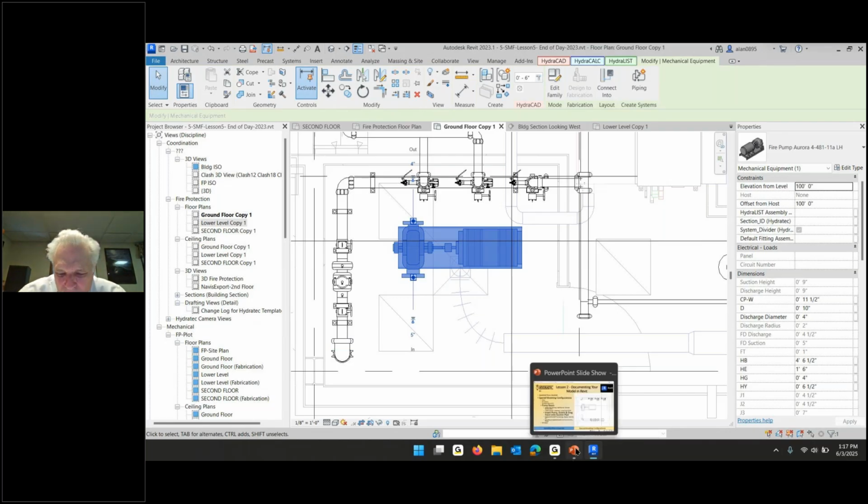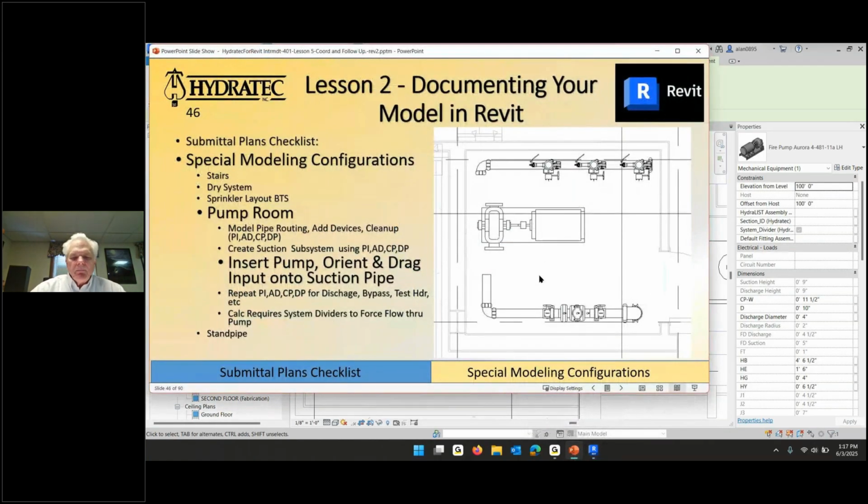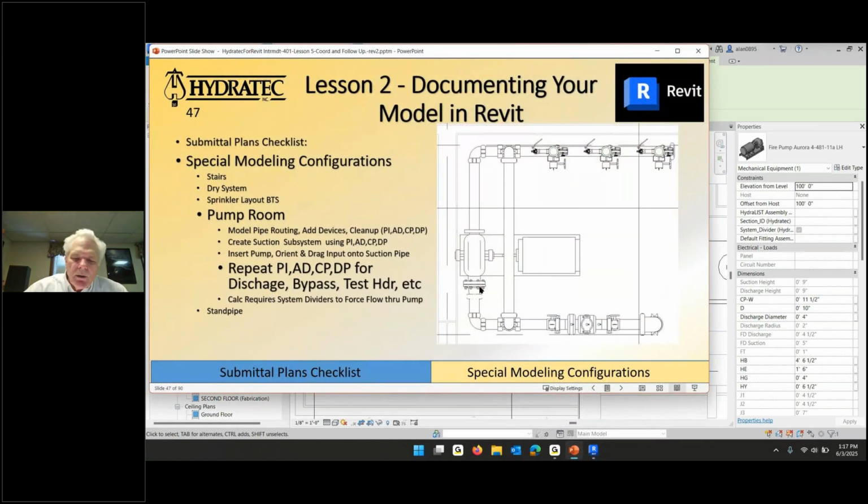The video, I'd say wait for it and watch for maybe an update to the toolbox, or at least a message about more videos. Helpful video fire pump, that's where I'll put it. I'm going to get fancy on how you put a flange set and how you put an eccentric reducer so it's flat on the top, and wire those things together. But the trick is do all the suction pipe, do the pump separate, rotate it so that it lines up, and then drag it onto, or use connect, to get the pump onto the suction pipe.